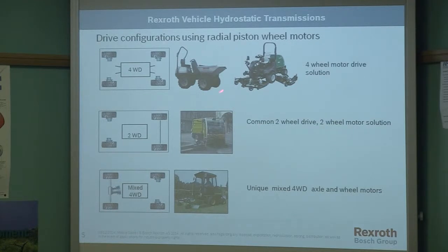And also, site dumpers are very, very price sensitive when it comes to selling hydraulics. So this is probably going to be the best cost-effective solution compared to the others. So, 1 to 2 tons wheel motors, 2 to 6 tons, it's what we saw on the earlier slide with bent axis, and then above 6 tons, it's generally non-hydrostatic. And I'm not just talking about one manufacturer there, that tends to be across the industry. And as I said, price is the major issue, I think, there.